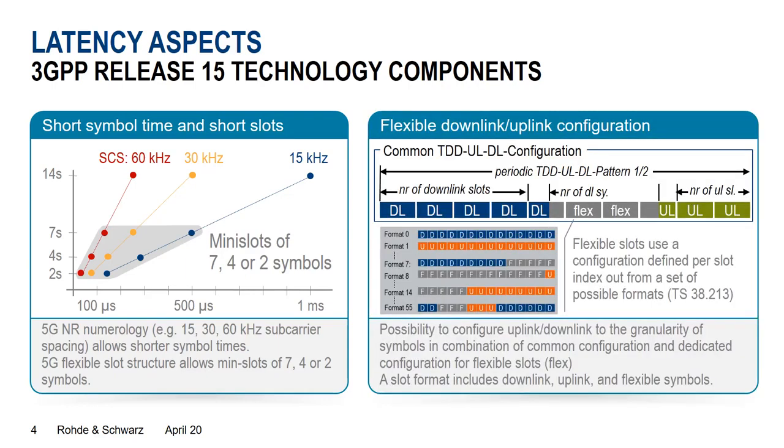So obviously, a mechanism to support low latency communication. Also, we are operating a TDD system, and that is again very flexible to be configured. You can see here the downlink and uplink slots that are allocated, and there is also the possibility for flexible slots. For these flexible slots, the number of downlink and uplink symbols is also very flexible. In that sense, you can choose from a variety of configuration possibilities to best support your own application. If that is a low latency application, then you obviously choose the right slot format for this.